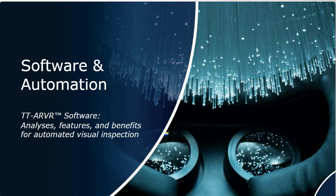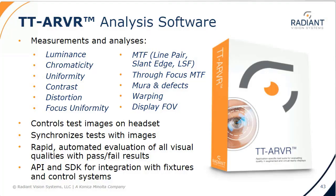The TT-ARVR platform provides a lot of power for display analysis as well as fully automated testing. Radiant developed its TrueTest ARVR software with analysis and functions most relevant to XR display measurements. Analyses in the TT-ARVR software platform include luminance, chromaticity, uniformity, contrast, distortion, focus uniformity, modulation transfer function, line pair, slant edge or LSF version, true focus MTF, mirror and defects, warping, and display field of view.